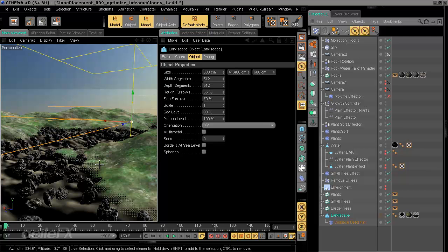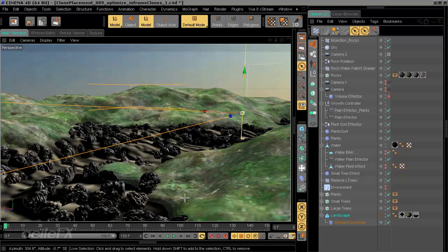But what we can also do is create a duplicate terrain to use to control the clones separate from the rendered version. So that is also a possibility. And in that case, you can sometimes use a lower res version just to get the initial placement. The main problem is for very fine areas that cut off and drop off, things like that, you might have some polygon overlapping.